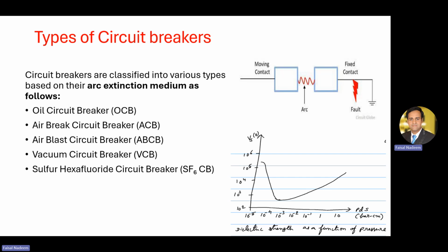the presence of the arc is due to the presence of highly ionized particles or molecules in the vicinity. If that arc remains, due to the thermodynamic ionic effect, the number of electrons or the arc creating medium will further increase and it will lead to a continuous avalanche process, resulting in an extremely high arc.